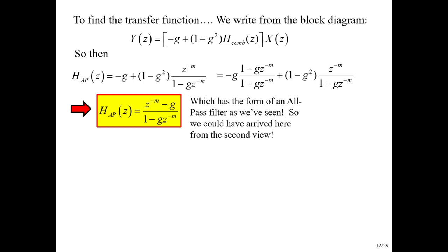And so we look at that, and now we know, in our modern view, how to characterize all-pass filters, and we said, oh, it's going to have this kind of crisscross relationship. I don't quite have this in the right form, but if I put this first, we'd see that crisscross of the relationship. But I've got these in the reverse order, so we see that we have a minus g and we have a 1. So that's the way that we talked about that before. So clearly this is an all-pass filter. And it has the same denominator that the comb filter had before.